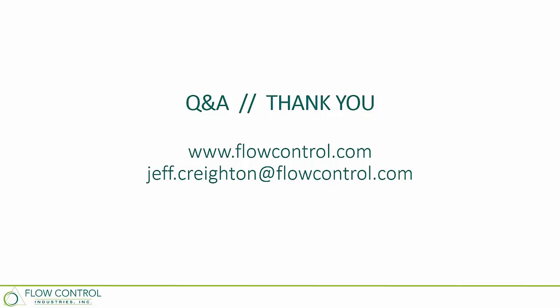Another question about, do we look at fan kilowatt energy as leaving air temperature was increased? One of the things that showed up on the Arizona campus, one of the buildings that was struggling when they were not getting enough cooling, the impact of that was leaving air temperatures were high. And because they were not providing enough cooling, the fans were running really hard and adding a lot of energy consumption to the building. So when we got water temperatures where they needed to be, and we got cooling out there, they were still able to do resets, but we saw almost a 25% reduction in electrical energy in one of the buildings alone because of the fan impact. So getting that cooling had a huge impact on the fan side.